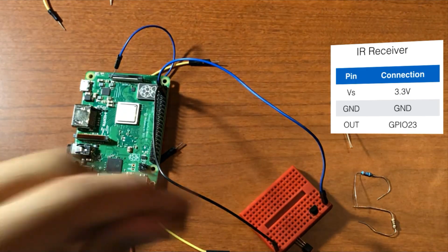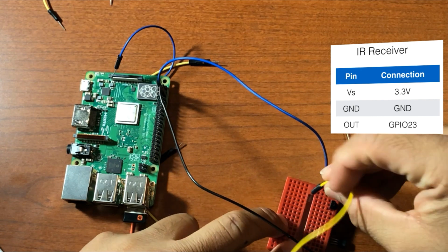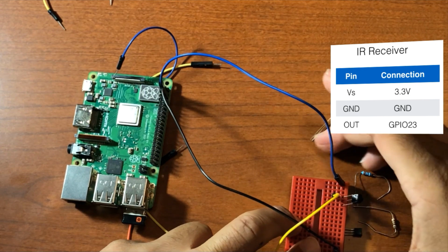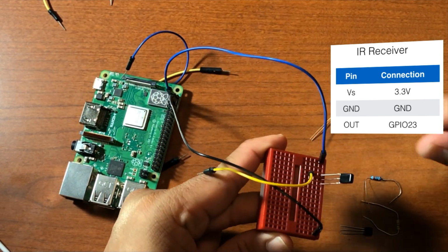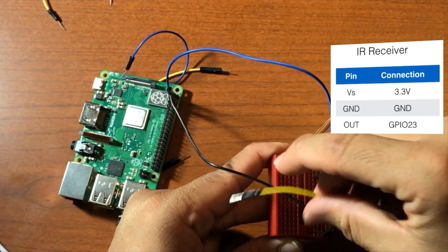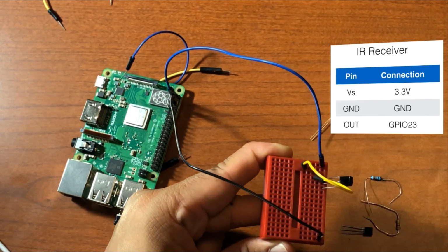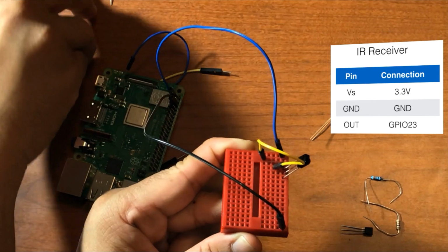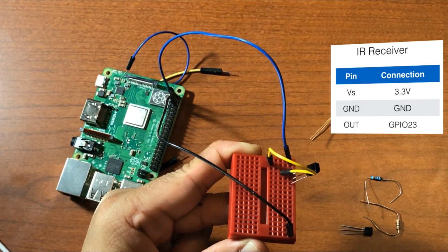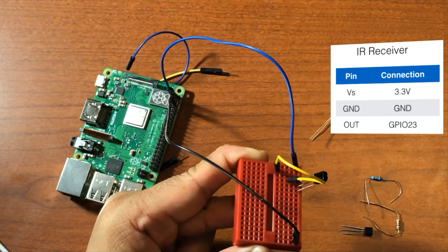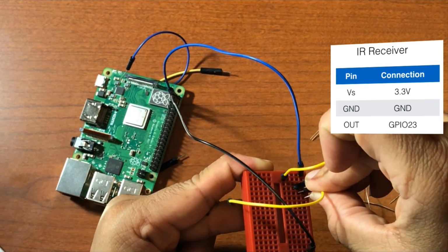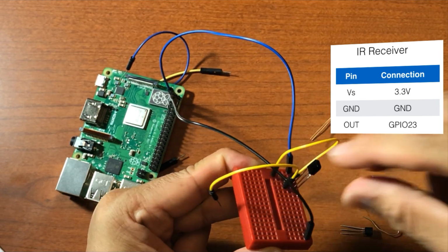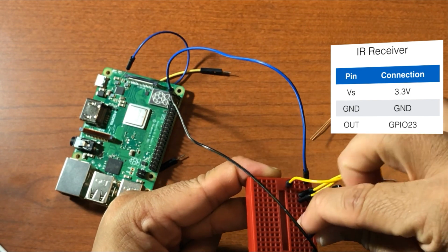So I'm just going to simply take a wire and connect it from the leftmost pin here to our 3.3 volt common. The center pin is going to go to ground. So I'm going to make that connection now. Here is the center. Match that up along to the center pin, and that's going to go to ground. So we'll make a connection to ground here.